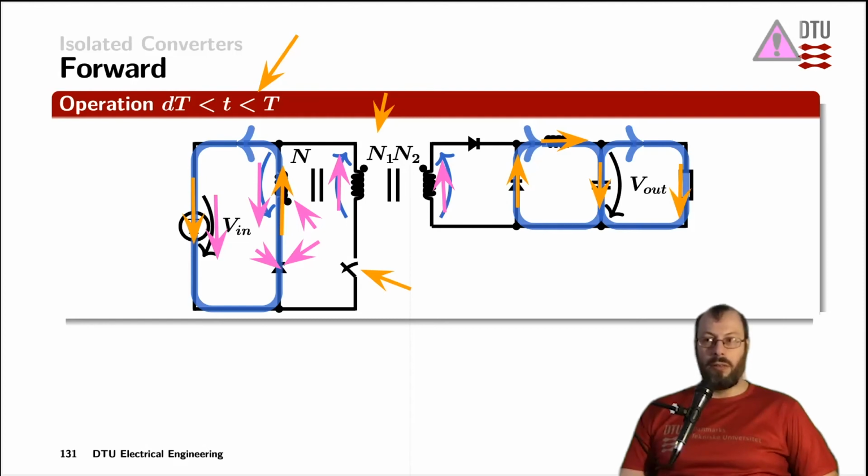On the secondary side, this voltage is equal to the blocking voltage across the diode here, as the freewheeling diode is turned on and shorts those two elements. And on the primary side, that means that the voltage up here is in series with the input voltage, and equally to the flyback converter, our switch has to block a higher voltage than the original input voltage of the DC source.